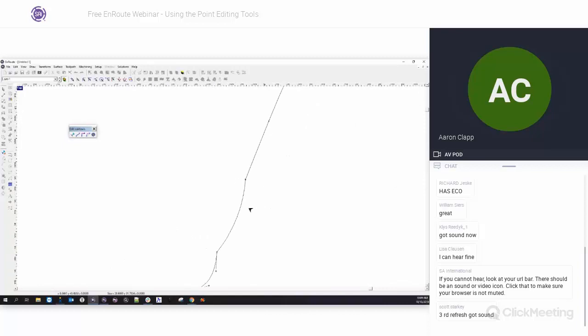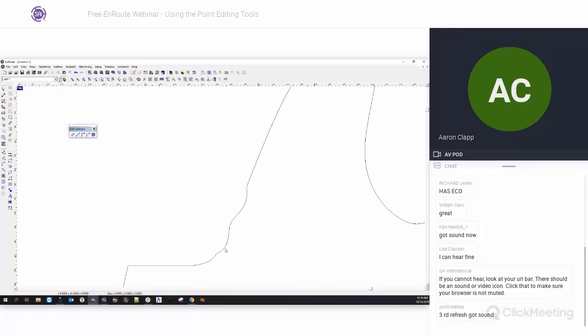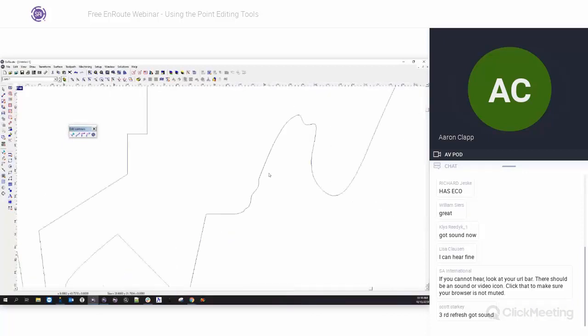One thing I can do is take this line, click on it, go up to the nodes, right click on the node, and say convert to a curve. When I do that, this line becomes a curve, and now I can use the same little editing handles to make changes to it. So something unique is that if you want to make fine-tune adjustments like that, Bezier-style adjustments, you can take any line and convert it into a curve or an arc.